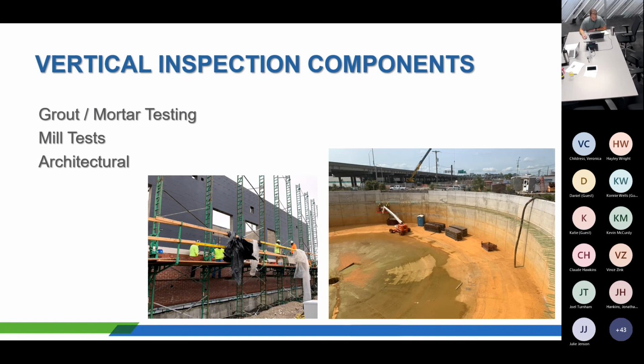Looking at mil tests for paint thickness and painting, or pull testing on painting, things like that. The Division 9 specs can have some pretty unique testing requirements buried within them, or manufacturer-specific testing depending on the product. So reading through those specs and understanding what's being asked to be applied to the project can be pretty important, as well as reading through those submittals as they come in.